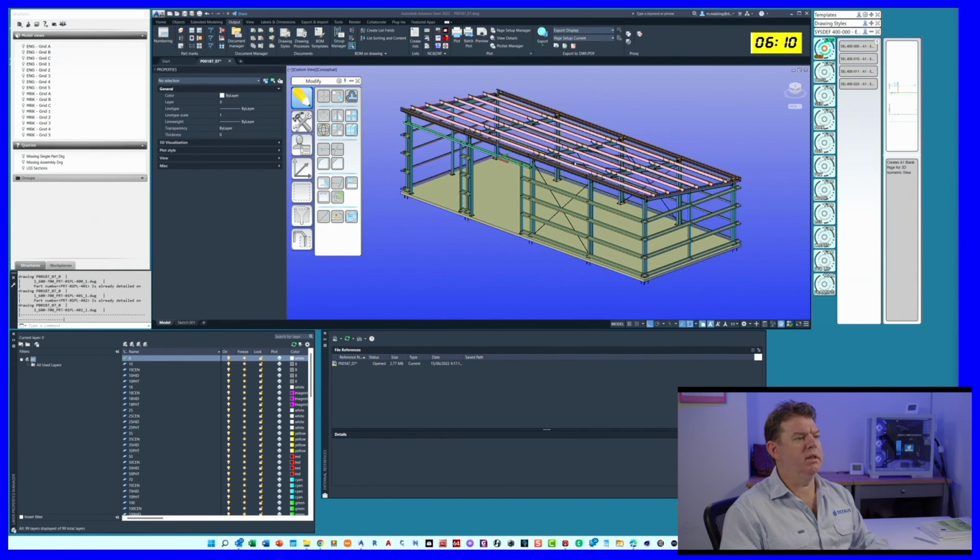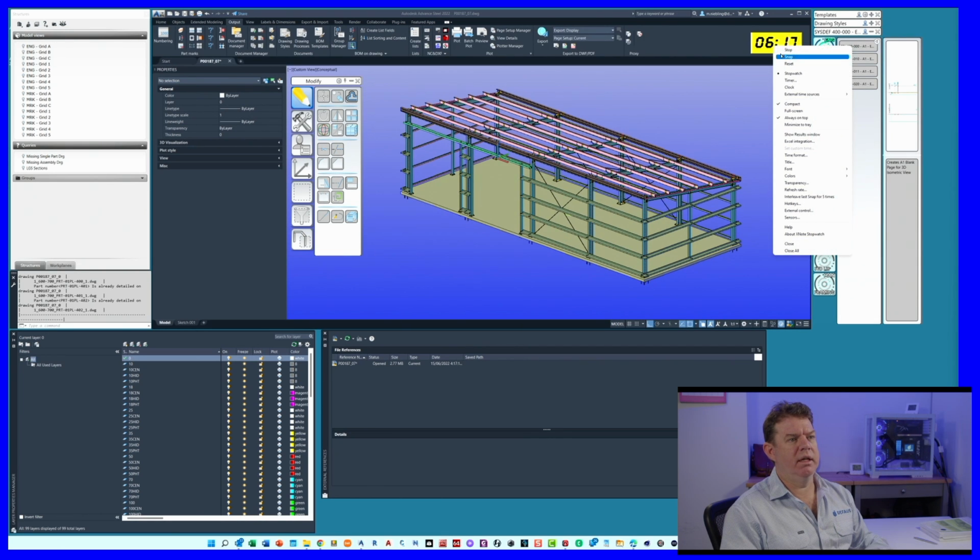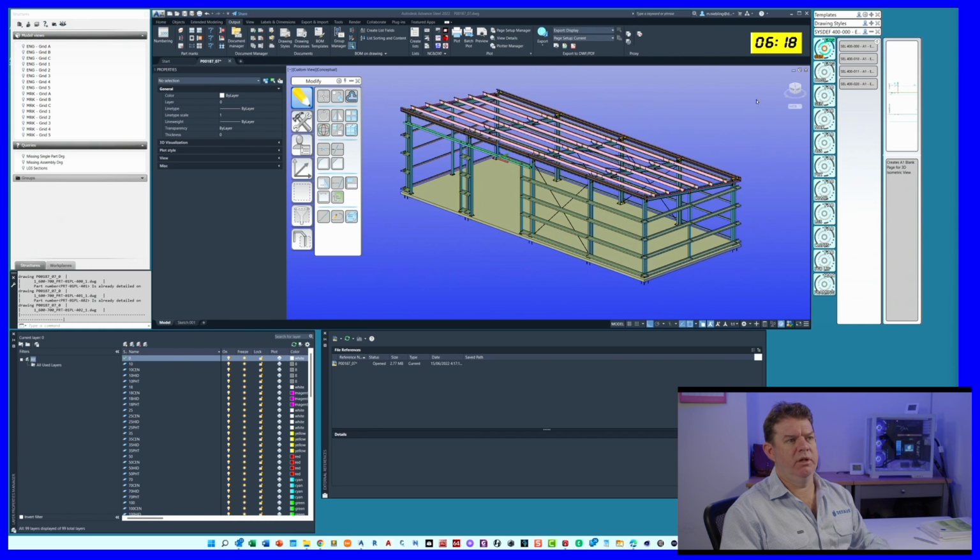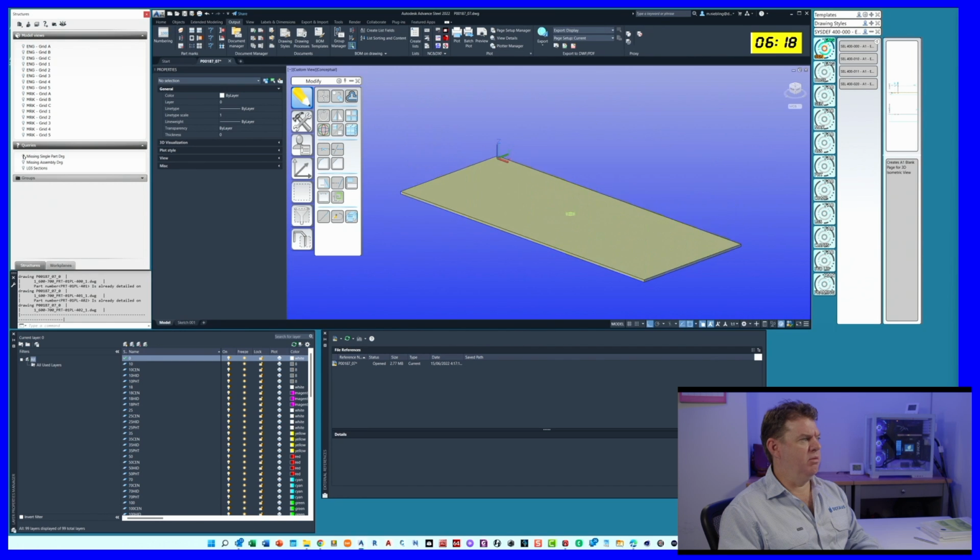Okay, it looks like that drawing process suite has completed, and it has taken just over 6 minutes to run that process through. So what we have done now is we have created both the engineering set and the fabrication set. The next thing that I would do is come over to my queries, and I have some queries for doing things like looking for missing single parts.